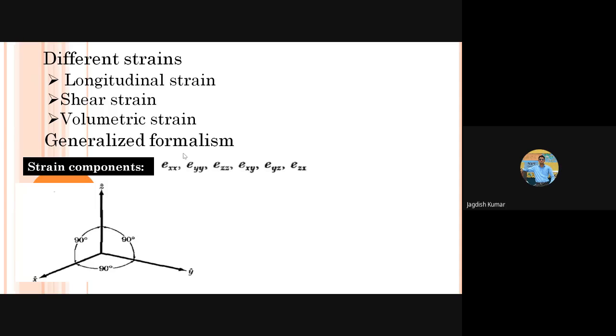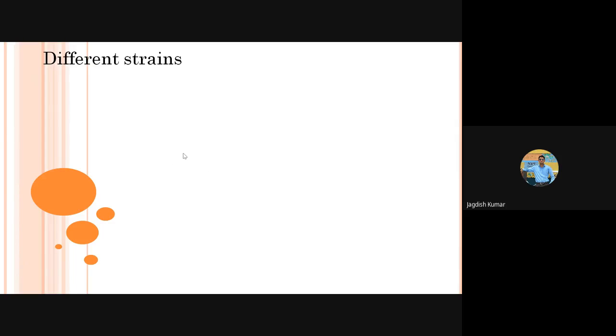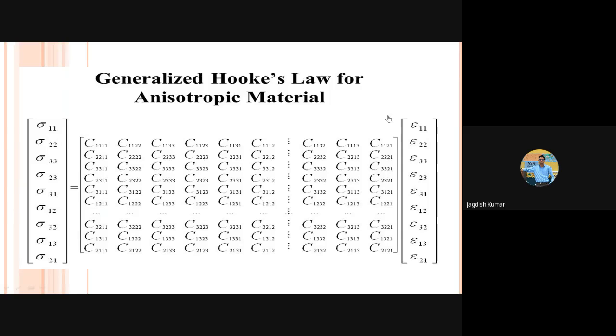Now let us define strain components. Earlier we were calling them epsilons. These are actually deformations, and deformation and strain are related to each other. The strain is deformation per unit length. That's strain. So suppose these are how many? 1, 2, 3, 4, 5, 6 components.